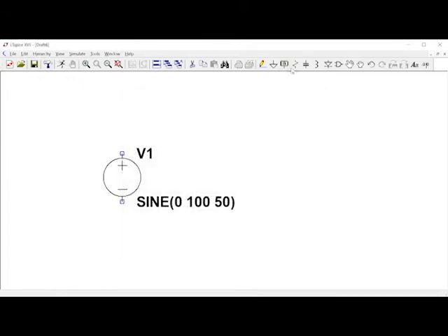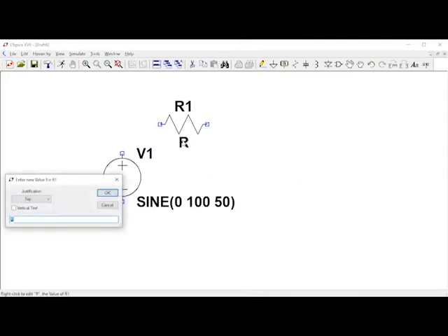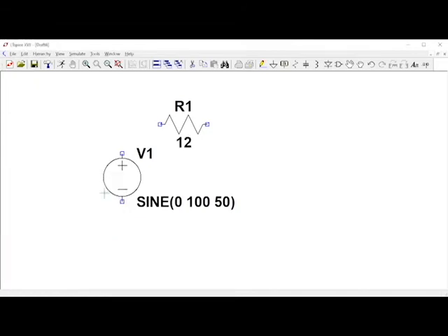Click on the resistor icon on the toolbar or press R. You can press Ctrl-R to rotate the component. Place your resistor accordingly on the canvas by clicking once. Press Escape to return to the selector cursor. Then right-click the R text on the bottom part of the resistor symbol. Enter your resistance value in the box. For this circuit, we will be using 12 ohms. Then click OK.